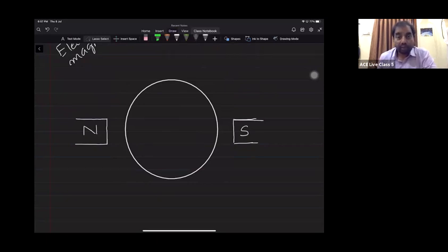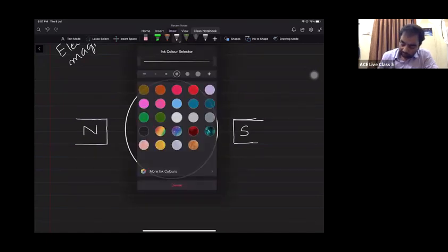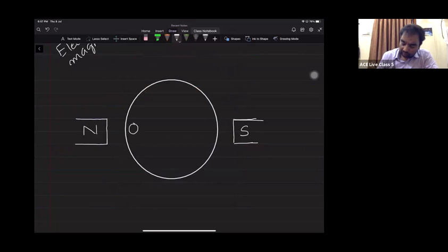You know that the armature core is also made of a magnetic material, steel. On the core we make slots, and in the slots we place conductors. Conductors here are not circular; they are inside, so the symbol seen from outside is a circle.